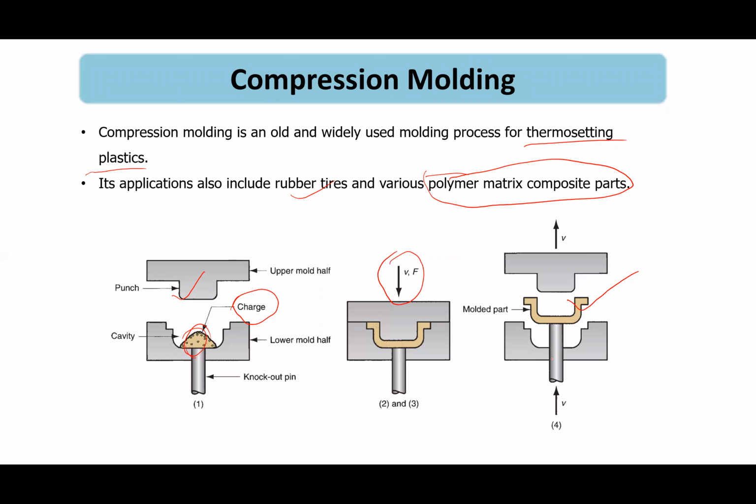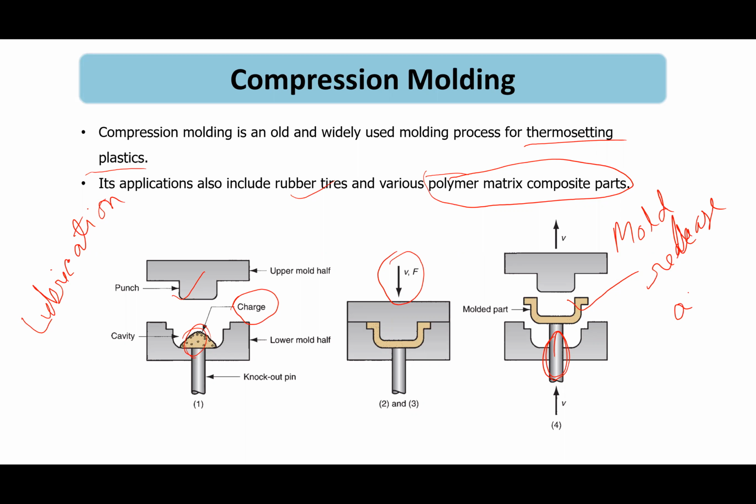For ejection, there should be an ejection pin, which actually ejects the molded part. And before you put the charge, you need to use lubrication for easy removal of the final molded part. The lubrication is a mold release agent. There are many variations of this mold release agent.